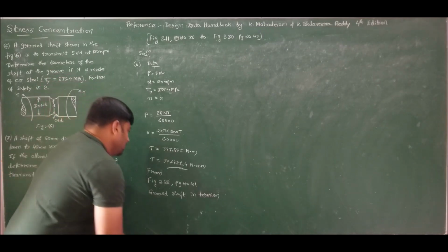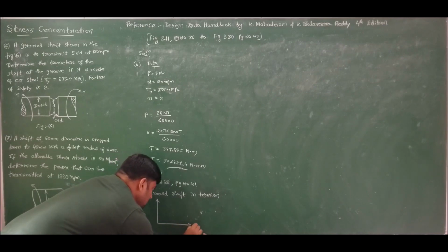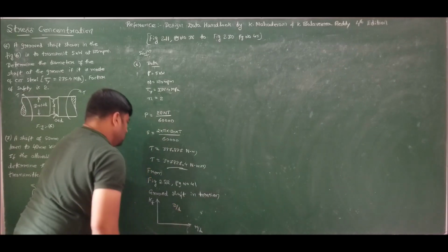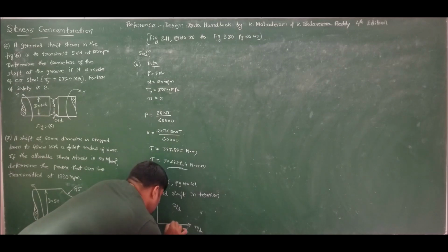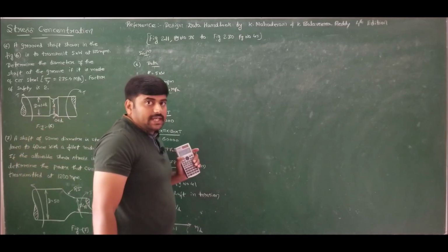If I observe this graph, we have the ratio of r by d, capital D by small d, and stress concentration. The x-axis is r by d, the y-axis is the stress concentration factor Kt, and curves of D by d are also presented. R by d is found to be 0.1, because radius is 0.1 d divided by d, and the d will get cancelled.